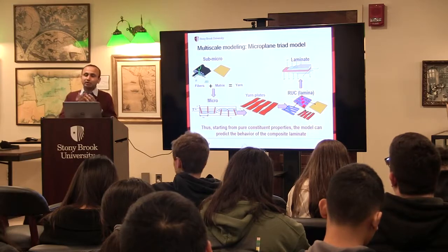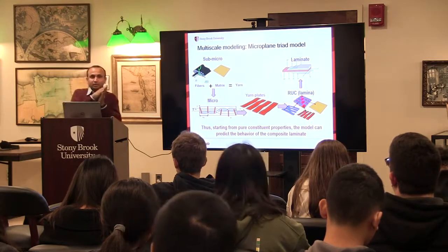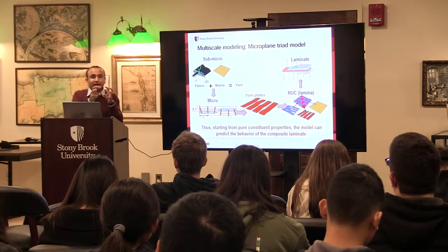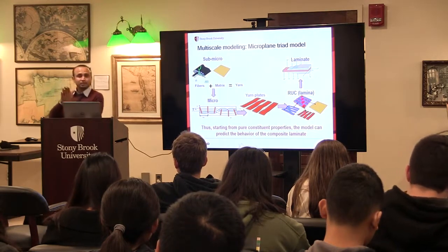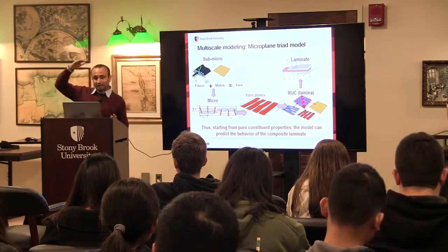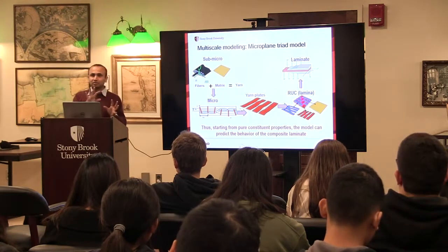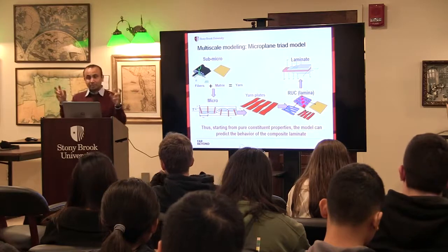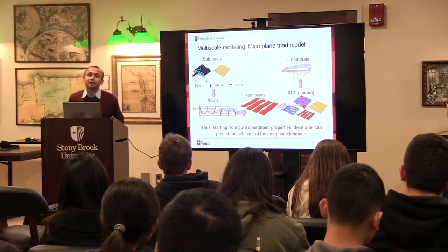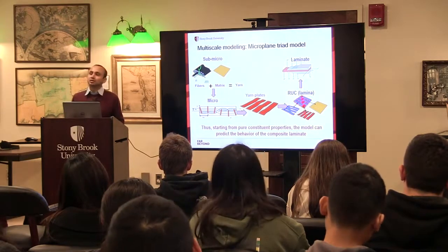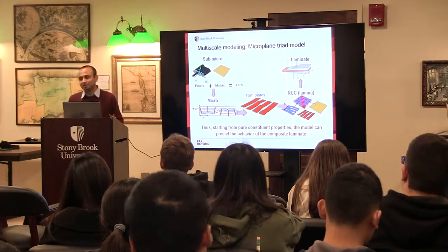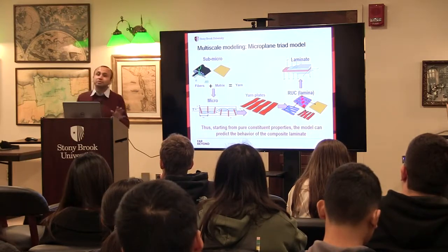So for example, if we know that tiny cracks are being formed between two fibers, we formulate that failure at the fiber level. If we know that the failure is occurring between layers, then we formulate that failure at the laminate level. And so this gives a mechanism-based structure to the model, and that helps with not fully, but at least partially overcoming this challenge of multiple failure mechanisms.